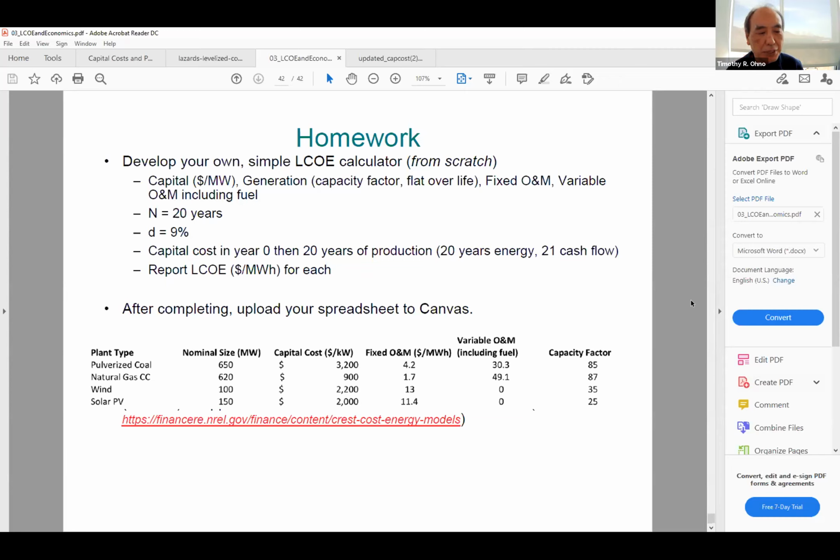In this particular case, what they said was, let's take these values for pulverized coal. So that means that I improve the efficiency of coal combustion by smashing it to pieces. So I've got an energy cost up front for doing the pulverization, but then the combustion efficiency is very, very high because it's almost a fluid, it's a powder. The second one is a combined cycle natural gas system. And time-wise, we'll have to see if we have enough time to talk about some of that.